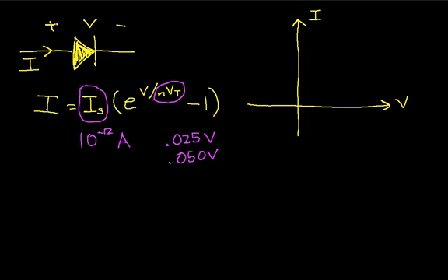Okay, so the diode has a fairly interesting VI characteristic, which we can plot using this equation and these typical values. When V is positive, the current's very nearly zero, starts to go up exponentially, and then at some threshold voltage actually takes off and becomes almost vertical.